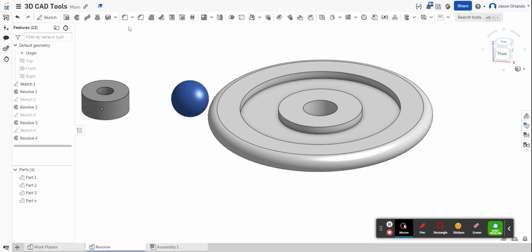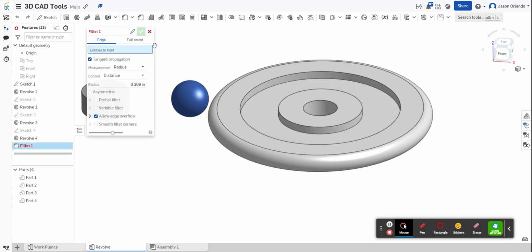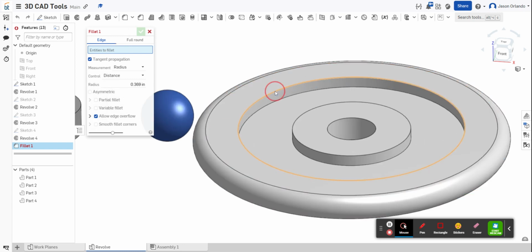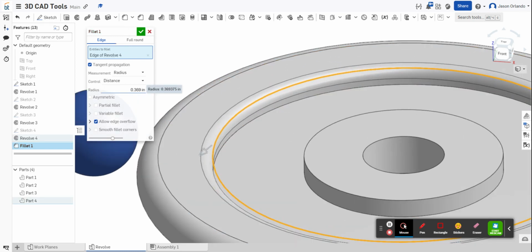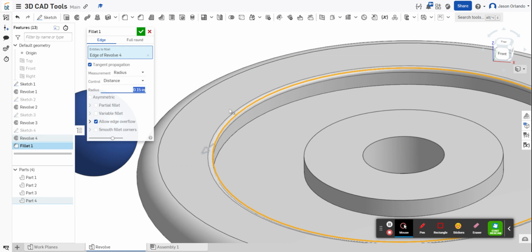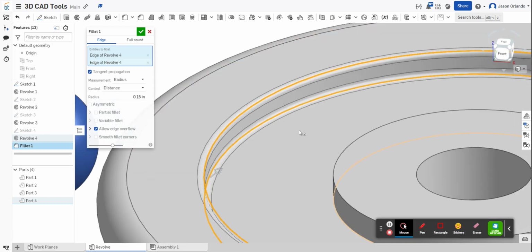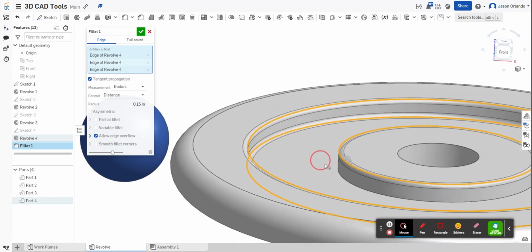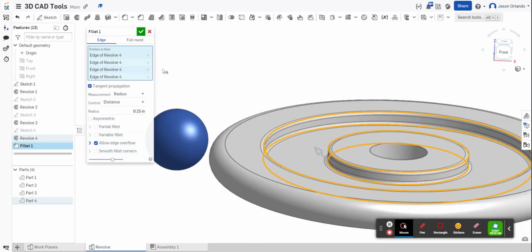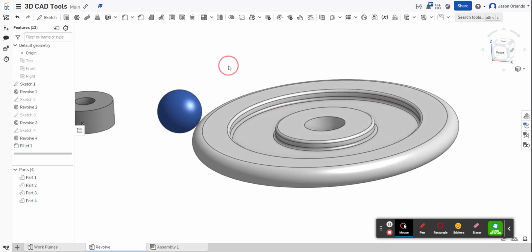And there you go. And then there are things that you could do after revolving that, like turning on the fillet tool to create an edge treatment to round over. I'll just change that to a smaller radius where you could round over and soften any corners, things like that. So there you go. That is the revolve tool.